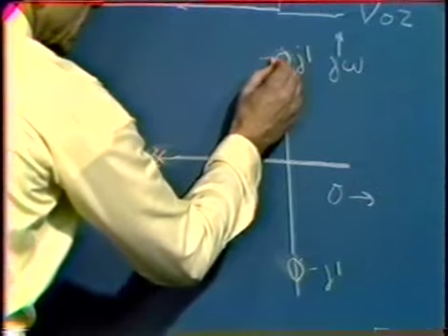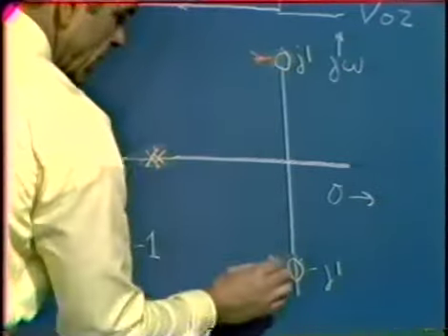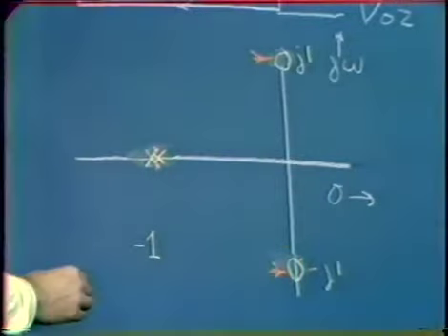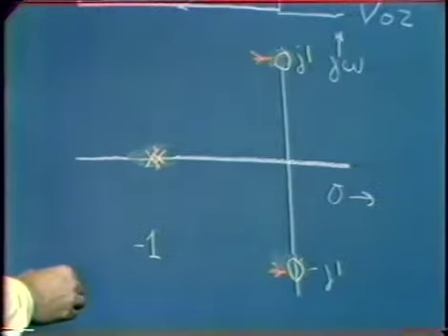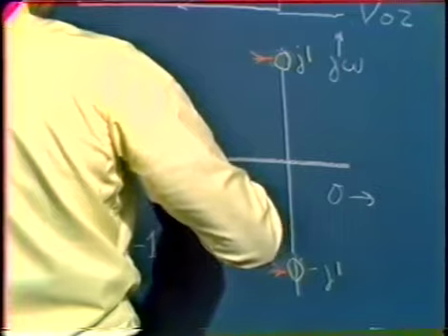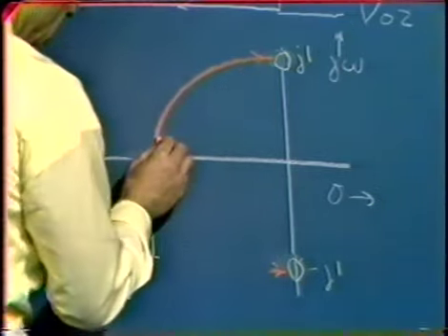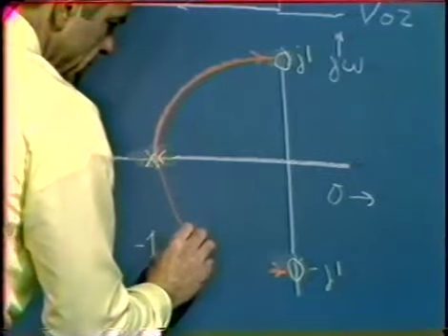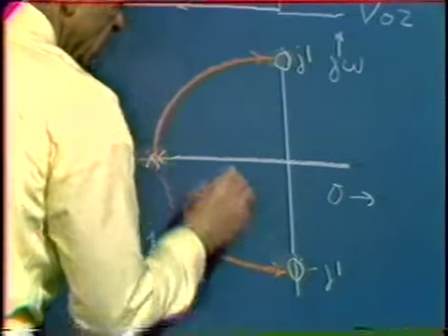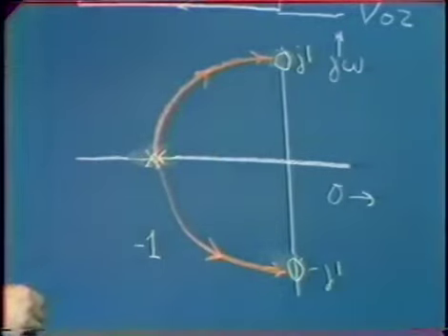We find out in that case that they reach the zeros like so, so the branches terminate in this way. And again, if we keep track of the geometry involved, we find out that the remaining part of the diagram has to be a circle or a semicircle. And so we get a root locus diagram that looks like so for increasing values of A naught, F naught in that direction.